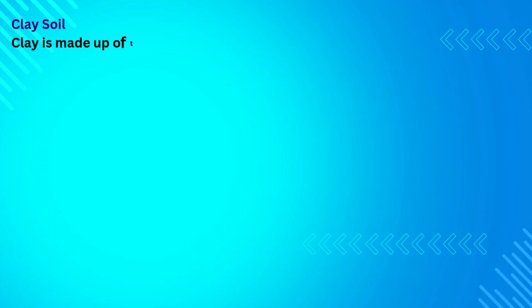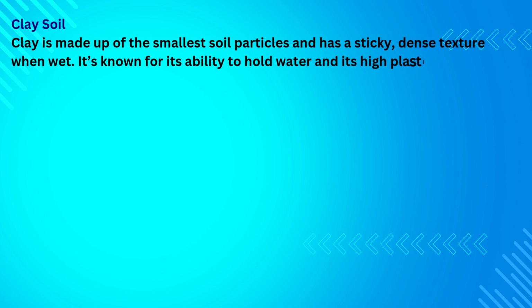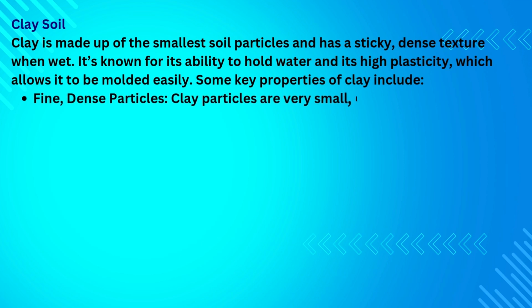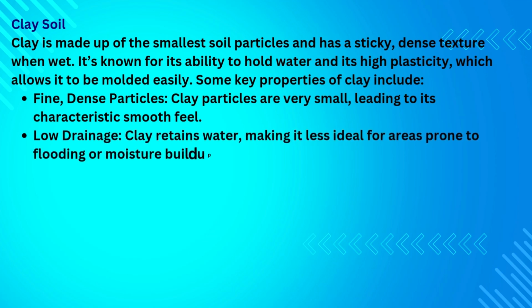Clay soil. Clay is made up of the smallest soil particles and has a sticky, dense texture when wet. It's known for its ability to hold water and its high plasticity, which allows it to be molded easily. Some key properties of clay include: fine, dense particles. Clay particles are very small, leading to its characteristic smooth feel. Low drainage. Clay retains water, making it less ideal for areas prone to flooding or moisture buildup.